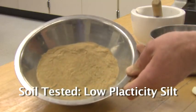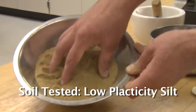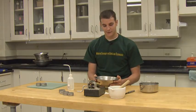The soil that we will be performing the limits test with today is a low-plasticity silt that comes from the Mississippi River Valley. This silt has been mechanically pulverized and then passed through a number 40 sieve to remove all large particles. For the purpose of today's lab experiment, bentonite clay has been added to increase the plasticity of the soil.